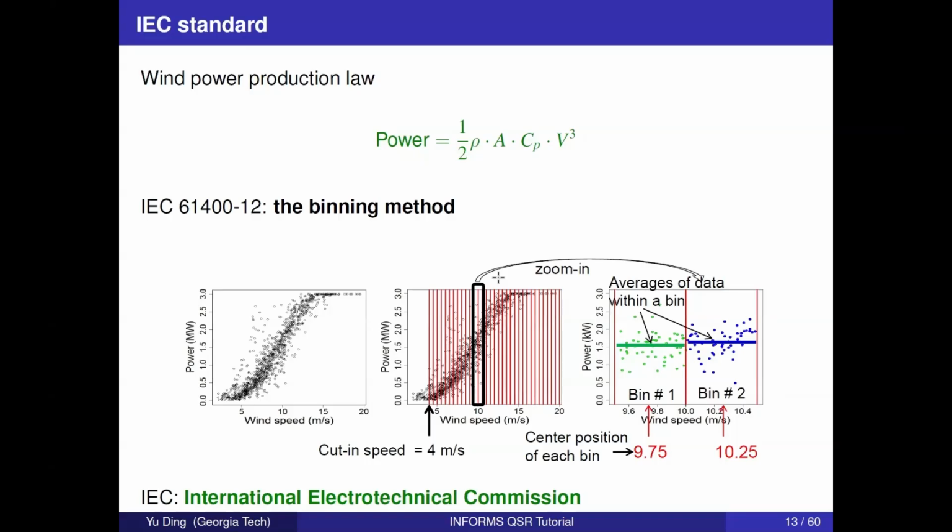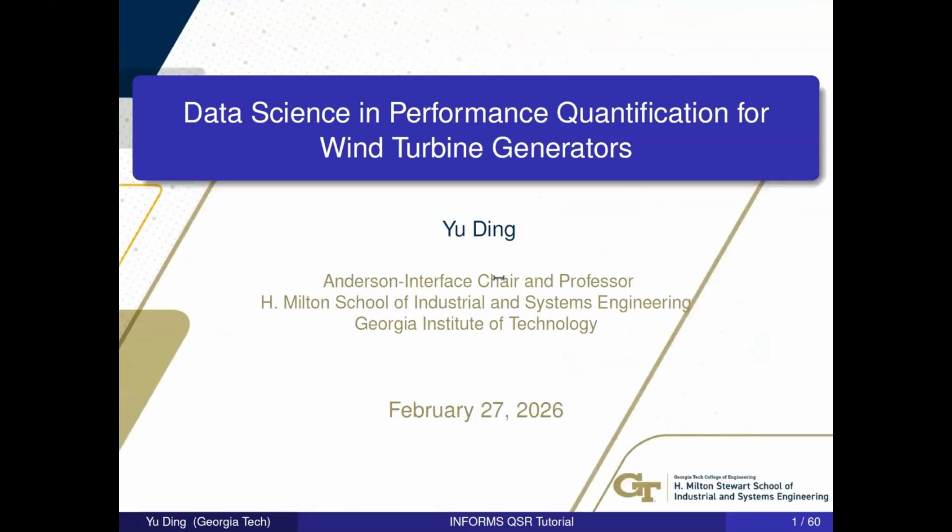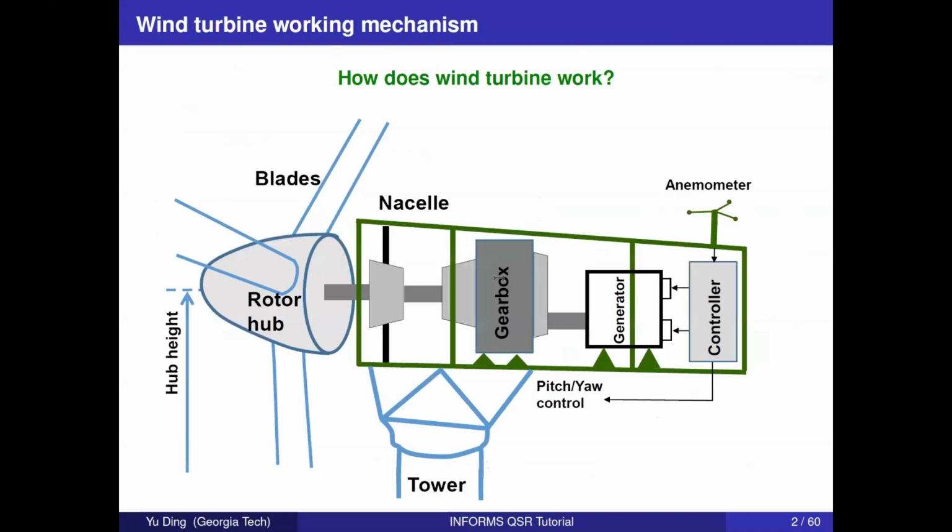Now, in the machine learning method, we can use the wind speed and wind direction as the input variables. The question is how you're going to learn that, right? What is the best way for you to learn that? There's an additional complexity to that. Currently, all the wind speed and wind direction are point measurements, right? If you look here, they are measured on the anemometer and the vane on the end of the nacelle.